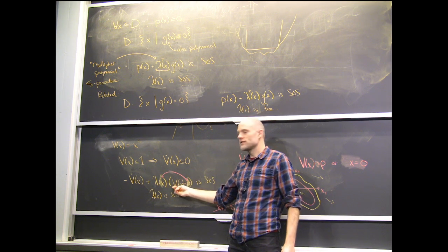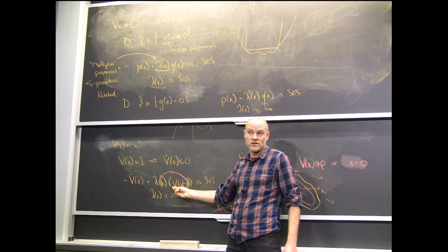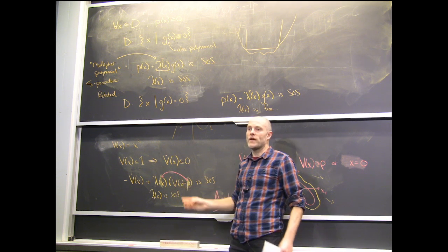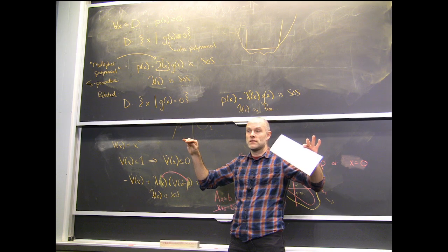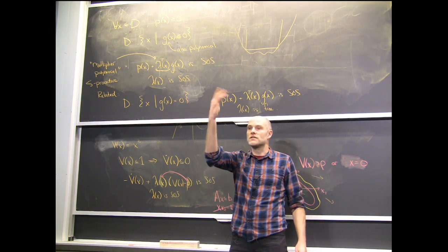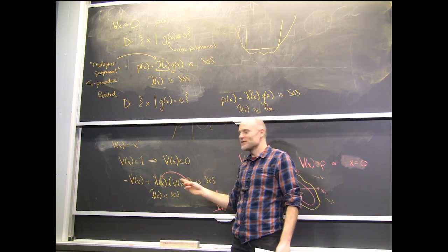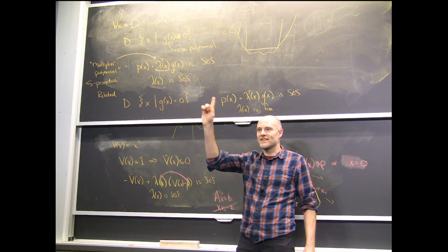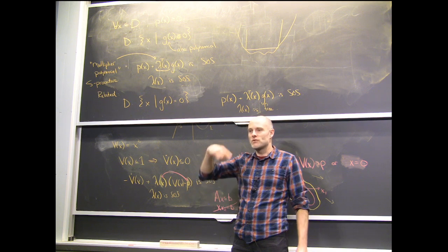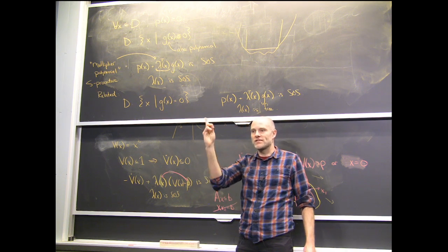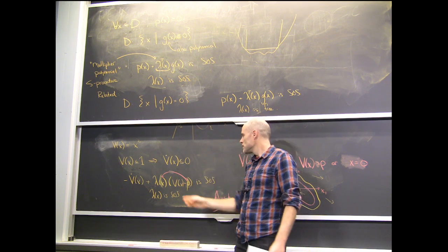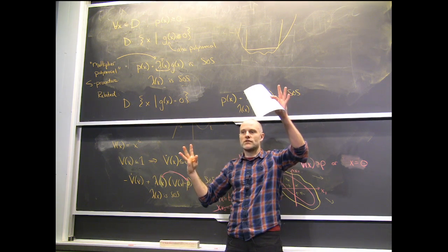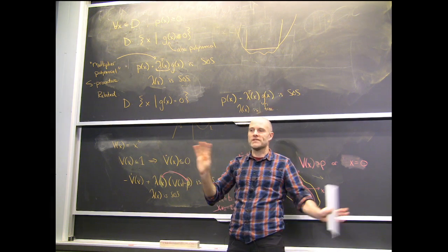You bring a cost to go function from your synthesis, and all you want to find is when can I trust that. For instance, if you want to certify when to switch from the energy pumping to the upright, remember we said that the energy shaping doesn't actually stabilize the upright, you have to switch to LQR. You could do that to compute the region of attraction of the LQR at the top and know exactly when to switch.